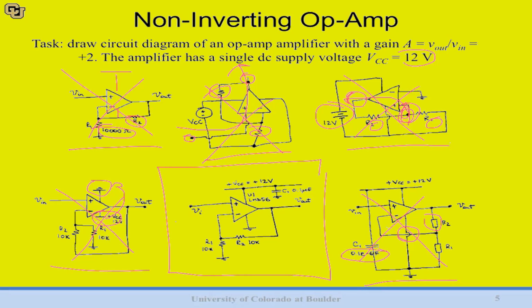The schematic that we really like is this middle one on the bottom. You can see we've labeled all of our components with designators or names. All of our components have values. We've labeled input and we've labeled output. You can see we use microfarads instead of 10 to the minus 6. Voltage rails are above ground rails. Data flow goes left to right. It looks really good. We like this one. Aim for something that looks like that when you're drawing circuits.